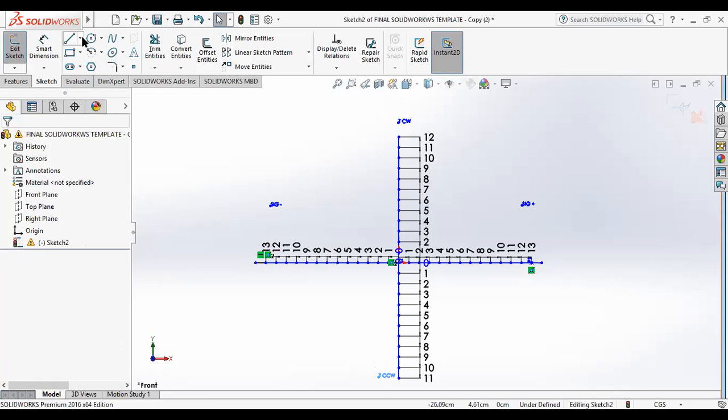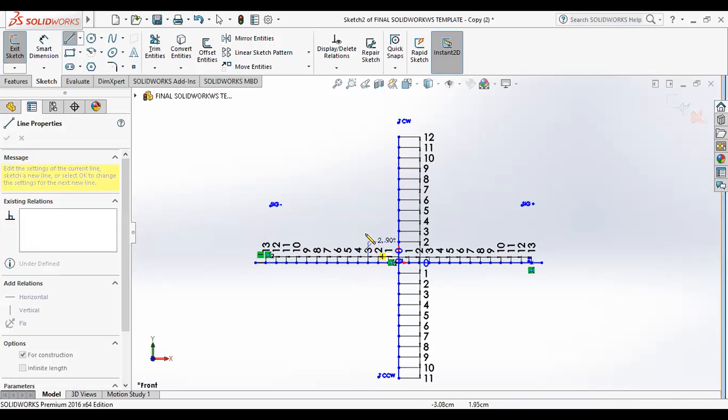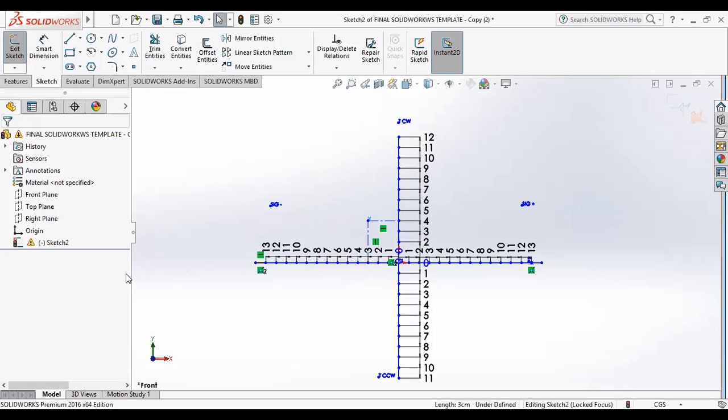So sigma is minus 30, and the x phase, on the y phase we have to look at. X phase it is minus 30. Minus 30 is here, sigma positive, sigma negative. And the x phase is rotating clockwise, minus 30 and 40. This is the point. Minus 30 and clockwise 40. You can draw a line like this and indicate this point as capital X. Okay, minus 30 and clockwise 40.